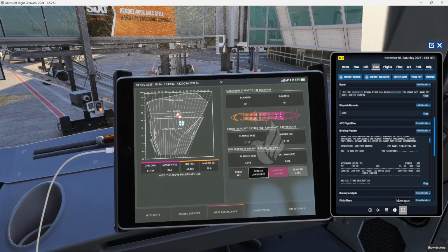Then if you take the dry operating mass and you add the traffic load, which is the baggage, packs, cargo, everything, here you get the zero fuel mass. You can calculate it in a different way; I'm going to give you a graph later on.